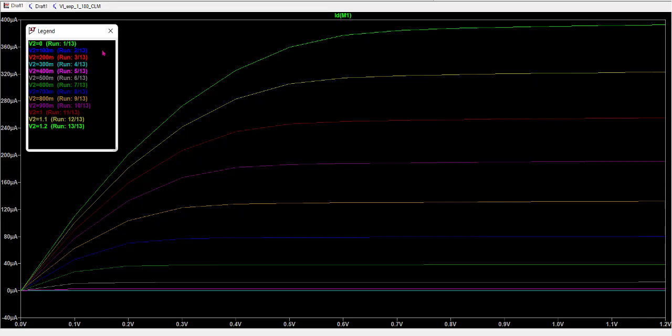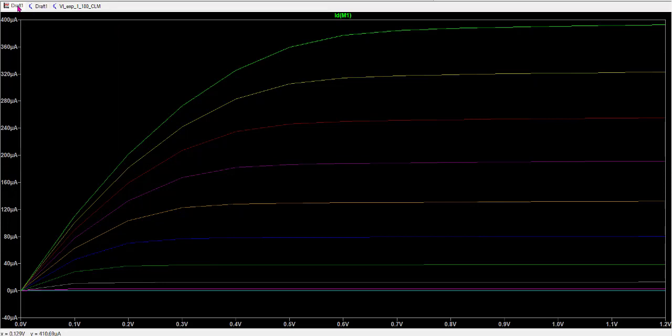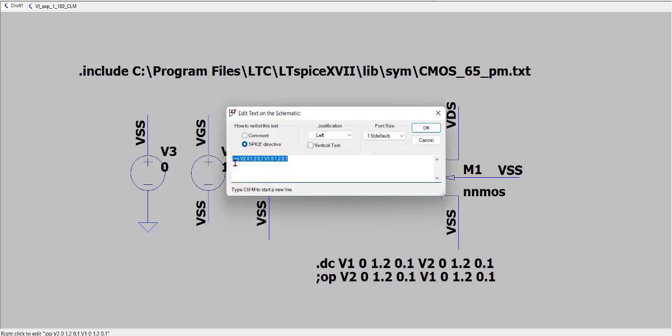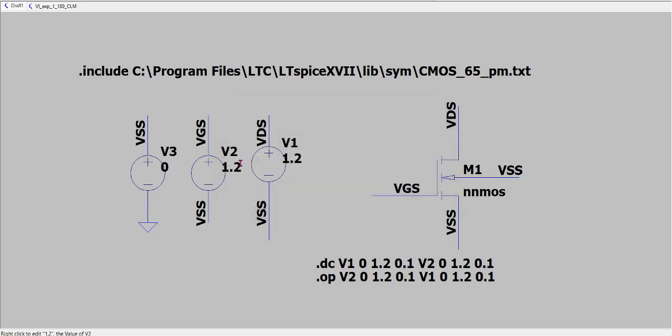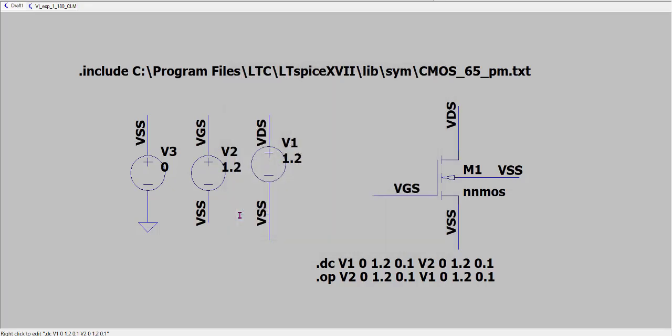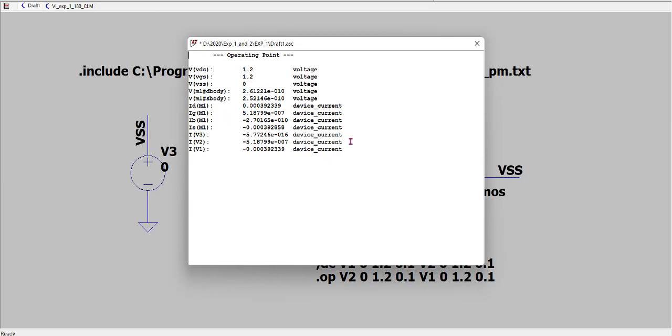Okay. So one more thing that I wanted to show you. Here's one interesting thing also. You can see that we saw that the VTH, that is the threshold voltage, was near about 0.5 volts. So let's verify that. For that there is an operation which finds out the DC operating point. So we'll just run that. And you see this is a DC operating point.